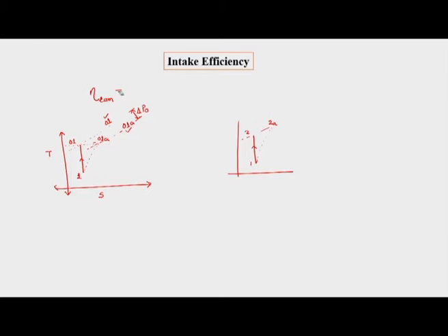Using this concept, we can see that the ramjet and scramjet intakes have their pressure rise not with mechanical pressure; they have pressure rise due to the shock, which is a thermodynamic effect, but that thermodynamic compression leads to the problem of loss in total pressure.